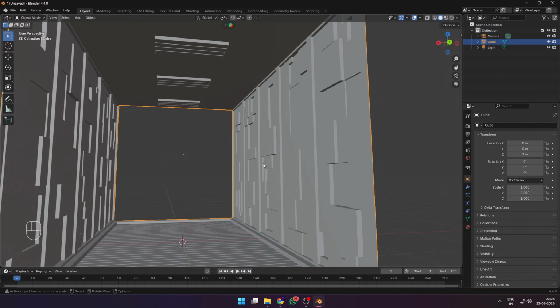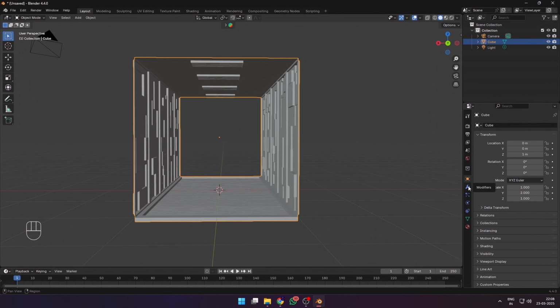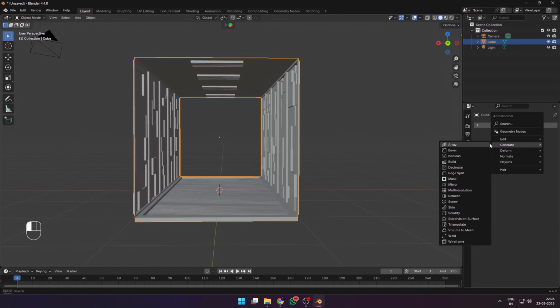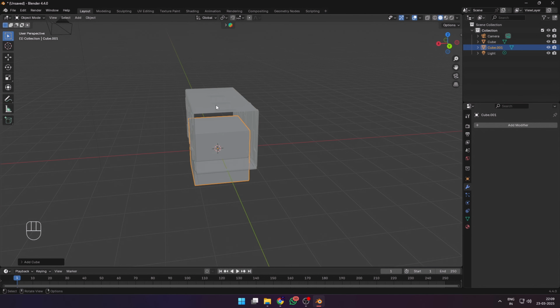On the right below the outliner, you have your side panel where you have your different settings such as rendering settings, output settings, modifiers, material settings, etc. Modifiers in Blender are like superpowers for your models. Instead of doing everything manually, they let you cheat time, duplicate, smooth or reshape things without actually editing the model. Think of them as non-destructive magic tricks that make 3D modeling way easier.